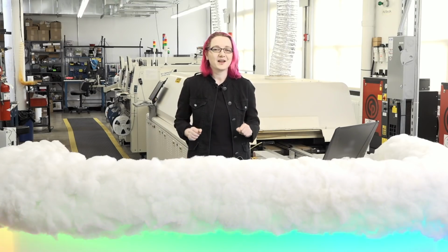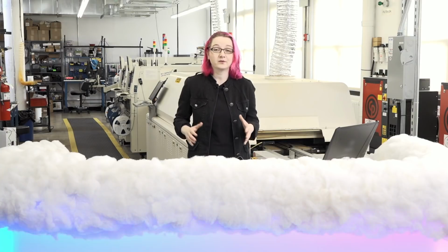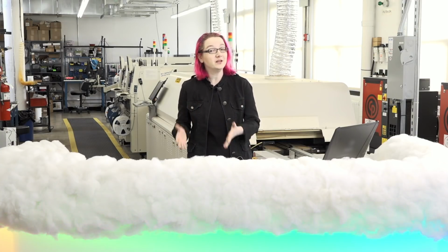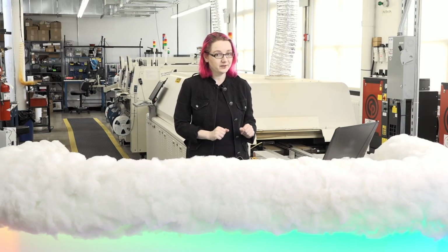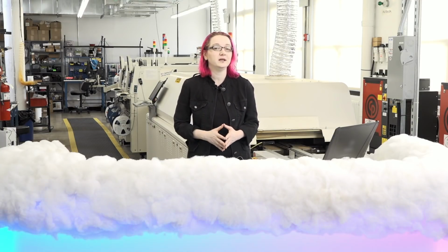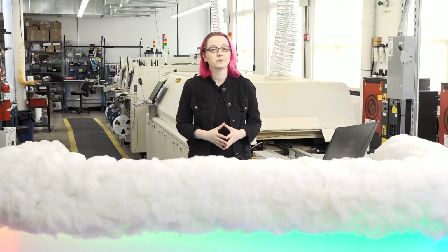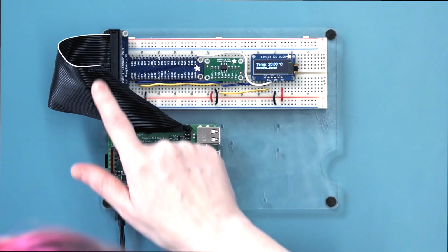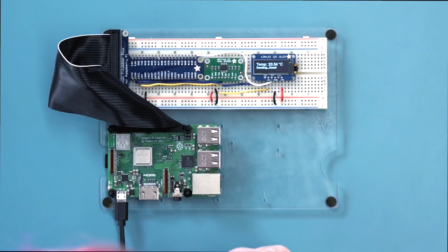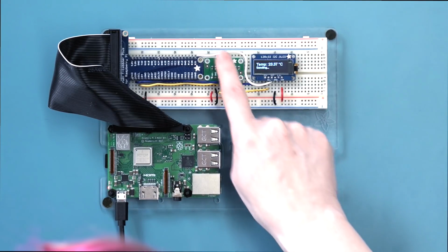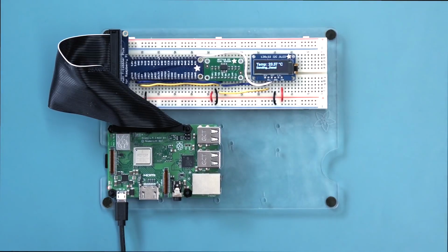Of course, now that we've got that feed set up, we'll want to automatically send data from our thing to it. Let's show how to do that with both a Raspberry Pi and Python, as well as a Feather ESP and C++ Arduino. Let's start with a Raspberry Pi with Python. We've already set up the Pi's operating system and Wi-Fi. We'll wire up the sensor over I2C and then run this Python script.